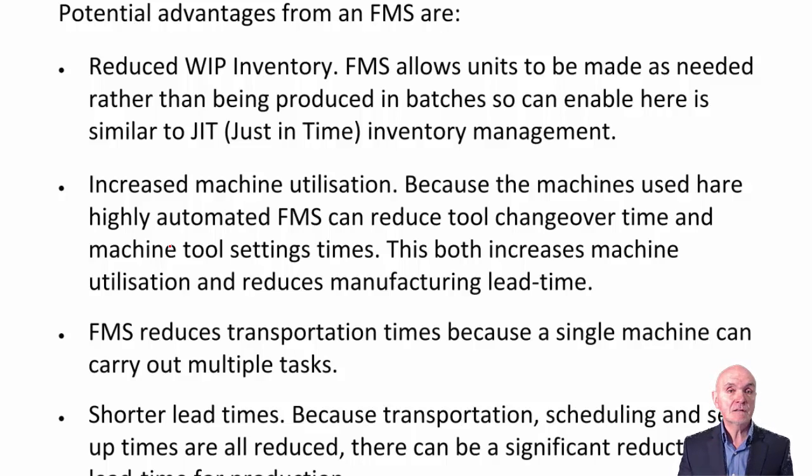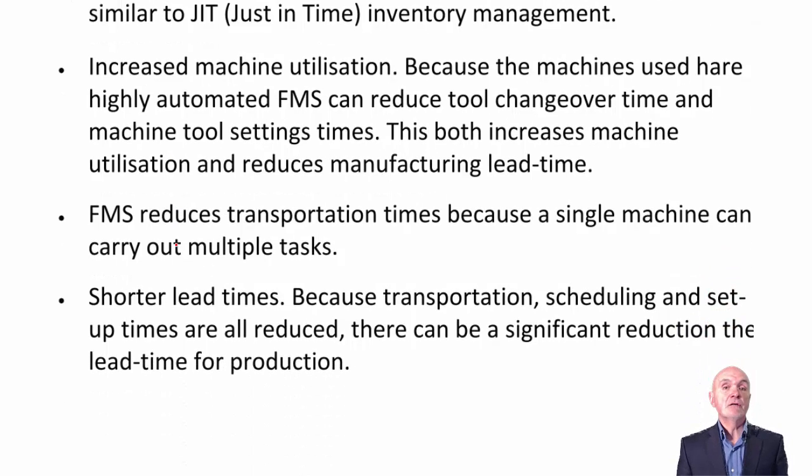You are getting increased machine utilization. The machine is now used for many purposes rather than one purpose. So whether it's drilling or cutting, the machine is still being used. It reduces the time and expense and danger of damage found in transportation from one machine to another. The product stays there, and different elements of the machine come in and quickly carry out another process on that product. And because all of this is cut down, the resetting of the machines is shorter, the transportation of the product is shorter, and so on.